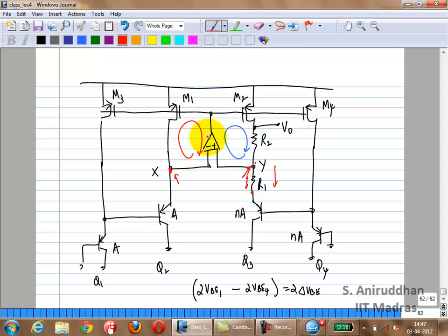Simple example, you have an amplifier, let's say a common source amplifier, with say a resistor which is insensitive to temperature. Right now assume that the resistance is constant with temperature. If you increase temperature, what do you expect the gain to do? Will it be constant, decrease or increase? Increase. Anybody? Everybody thinks it will increase? Okay, so I take a common source amplifier.